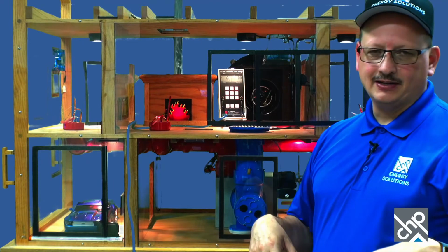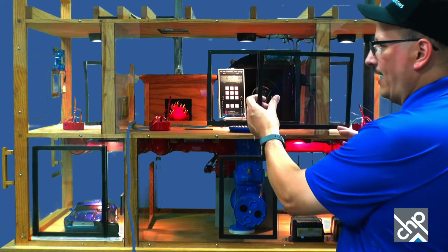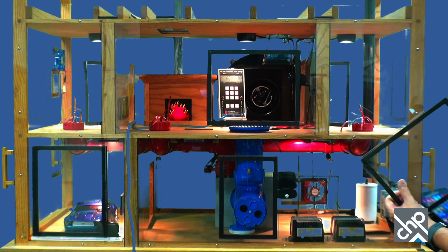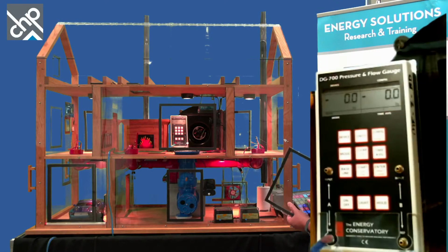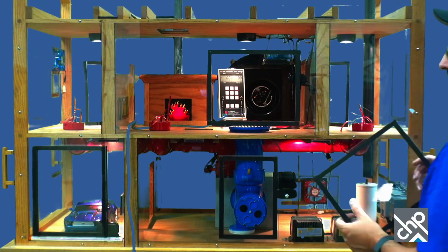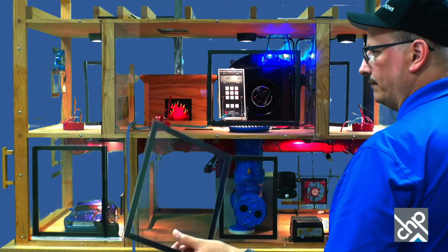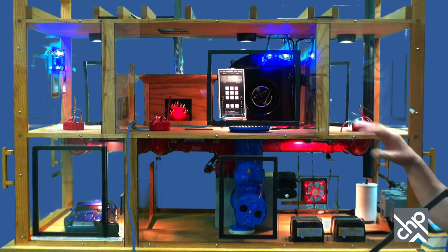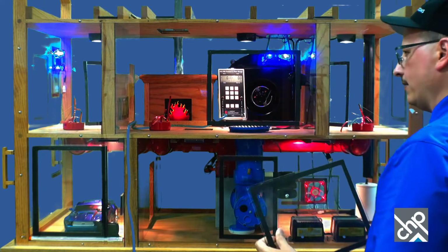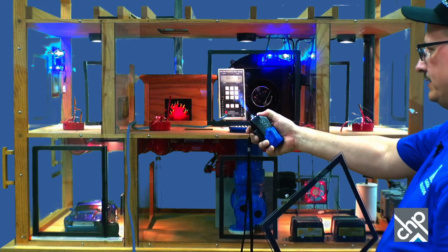If it's sucking on the chimney, as the house gets tighter, you might see the smoke come back in. But right now, we've got a really leaky house, and you can see the manometer, the pressure inside there, as well. So if I go back out here, you can see inside there that there's zero pressure. And then I'll go back inside, and I'm going to start turning on the exhaust fans. Here's the kitchen fan. Here's a bathroom fan over there, and then down on the bottom is the dryer. All of those are sucking air out, but it's really easy for them to pull air in through a really leaky house. They can pull it in through leaks in the building and stuff like that.